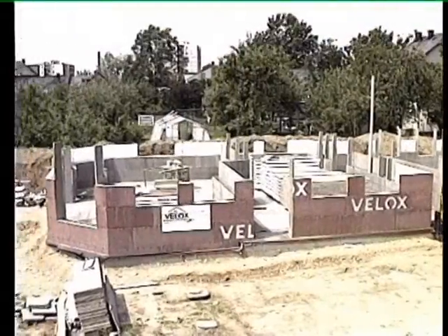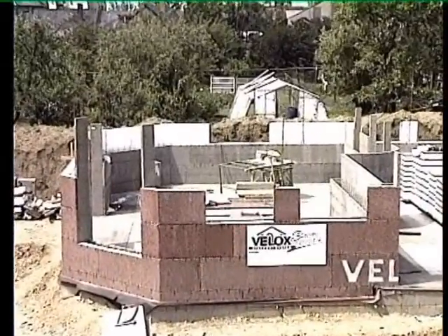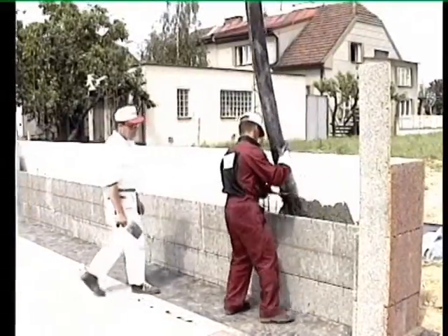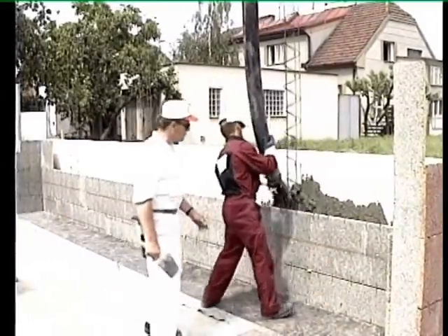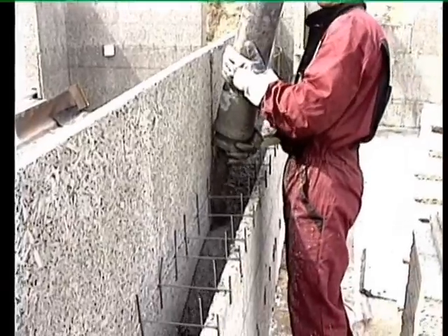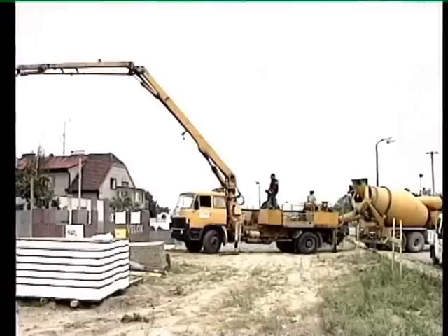After the first row is installed and leveled, the space between the boards is filled with concrete up to the height of approximately 400 millimeters. We first poured concrete at our building after the second row of boards had been installed. This is also possible from a technological and time sequence perspective.